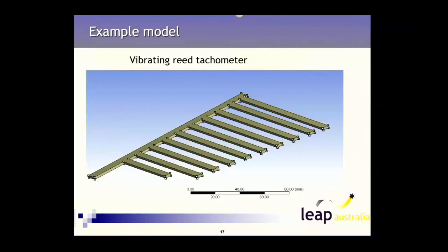So in the up and down and then left to right directions, the frequencies will be quite low. So the axial modes of these fingers will be quite high. So even though a modal analysis may pick up those frequencies, they may be a lot higher than the particular frequency that you're putting into this device.